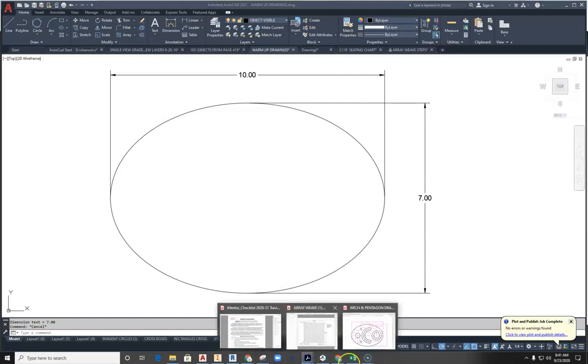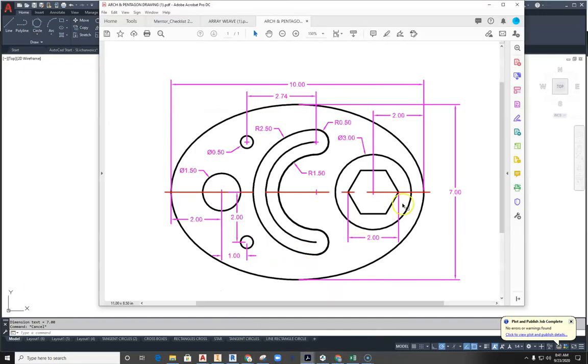Now, let's jump back and take a look at this drawing. The next step, we've got to talk about what drives the drawing. Let's talk about these dimensions. The dimension here, I know that I've got to go from this point over 2 to find this center location for this 1, 2, 3, 4, 5, 6. 6 is an octagon. No, that's 8. So this is a hexagon. To find the center of the hexagon. And then, of course, this circle is going to be concentric with that center.